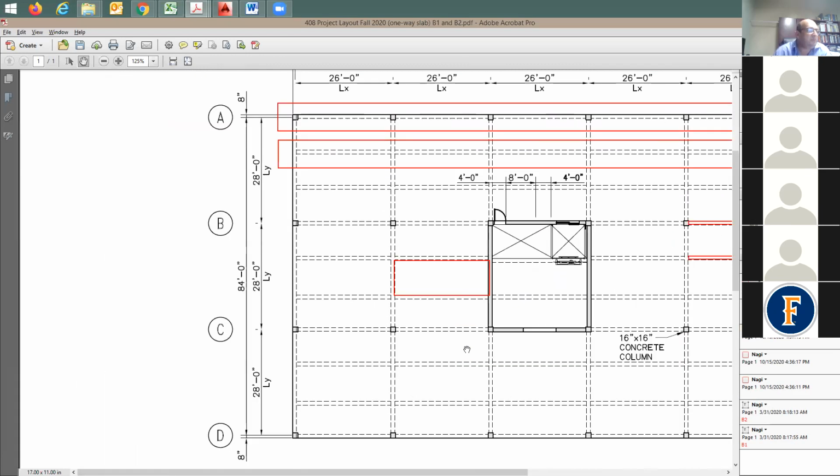It seems to me that all of these beams are put at equal space. So the spacing between one beam and the other beam is going to be equal to 28 feet divided by how much? Abigail? Yeah. All right, Mateo. All right, good. So how much is this? It's going to be 9 feet and how much? And 4 inches. Does this make sense? Yes? Yes. Okay, very good. All right.